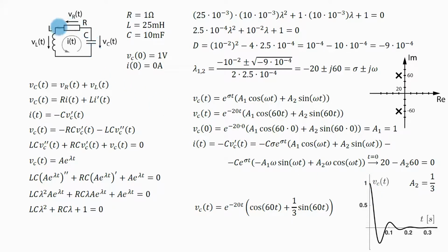Now, as this current is flowing through this inductor, that inductor is storing the energy of that current in its magnetic field. So as that capacitor discharges itself to 0, that energy stored in the magnetic field of this inductor will keep the current flowing, and it will start to charge this capacitor again, but to negative voltage.